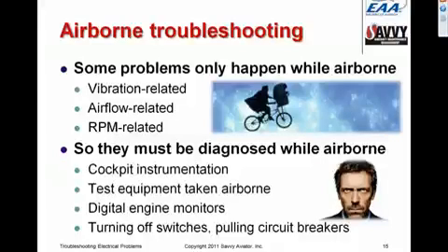And finally, as we talked about, a lot of problems are troubleshot in the air in a very rudimentary fashion, simply by turning off switches, pulling circuit breakers, and seeing what you have to turn off to make whatever the problem is go away. And so we do a lot of fault isolation in that fashion.